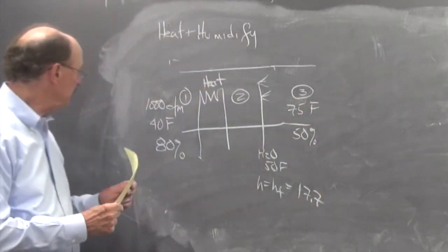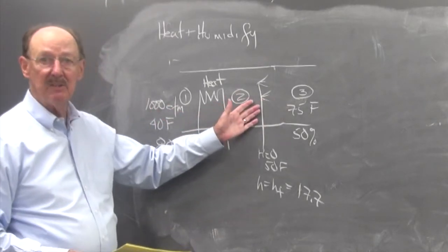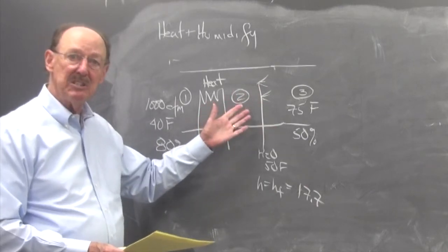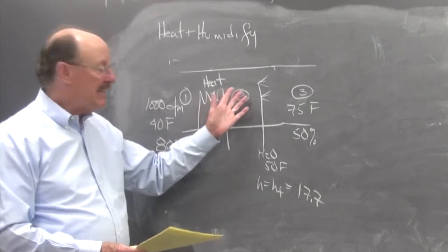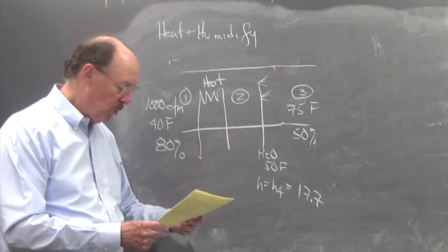So we start here, and we want this, and we have to humidify to get there. In heating systems, there will sometimes be a built-in humidifier that will have water vapor evaporate into the warmed air.